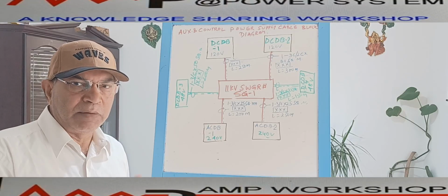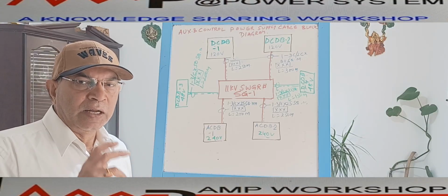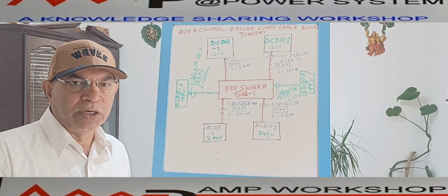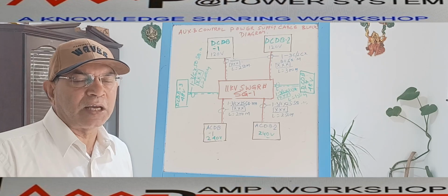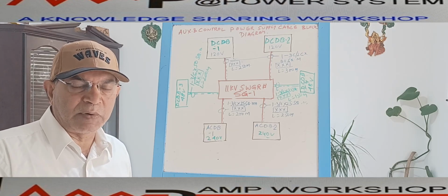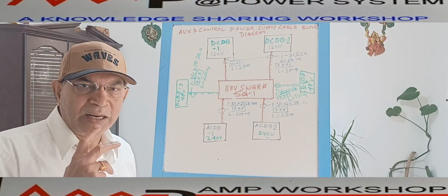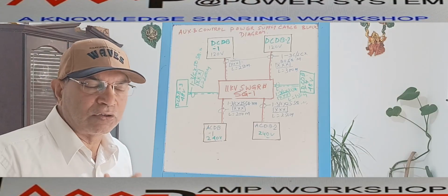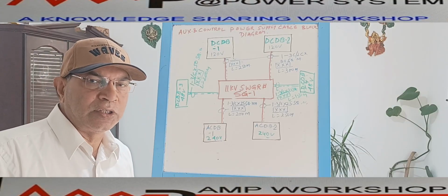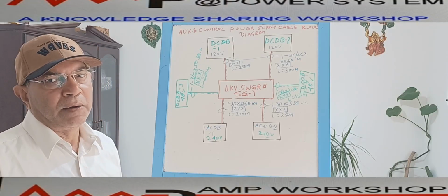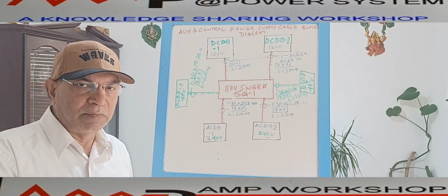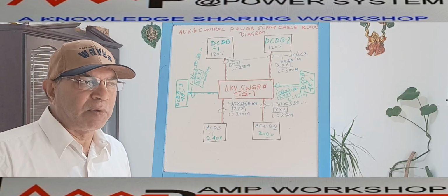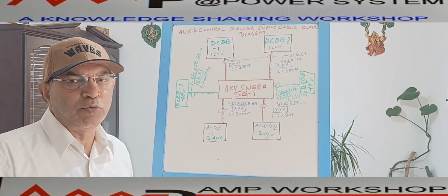If during a control power supply failure there is an abnormal condition in the main power circuit, then the circuit breaker needs to trip. If the circuit breaker fails to trip due to this control supply failure, then there will be a danger for the power system. That's why this DC power, either 120 volt DC or 48 volt DC, we always give two power supplies to this equipment, to this switchgear. So the two power supplies are coming from two different DC UPS systems.